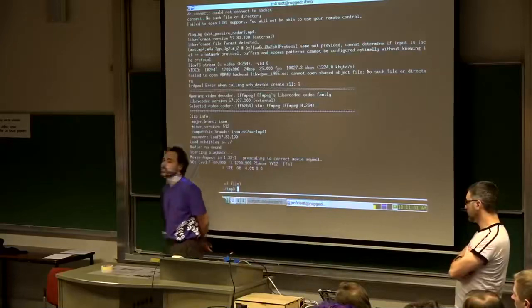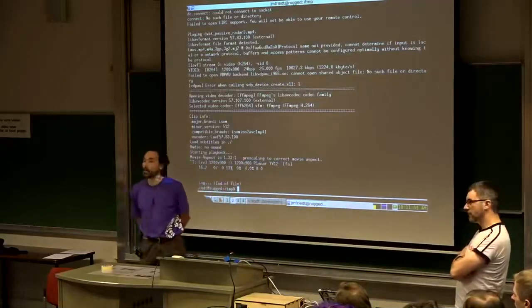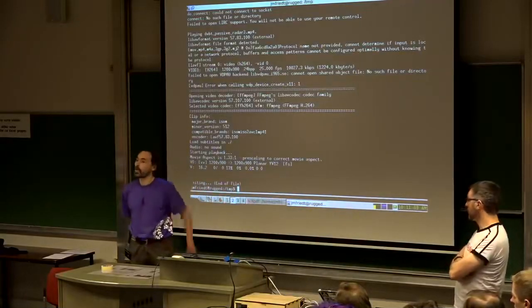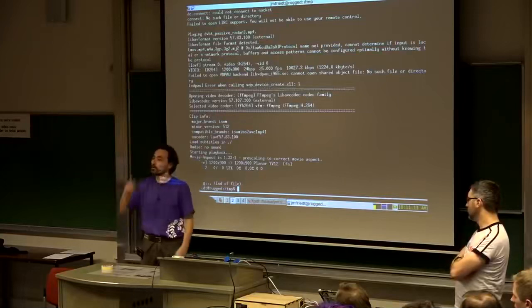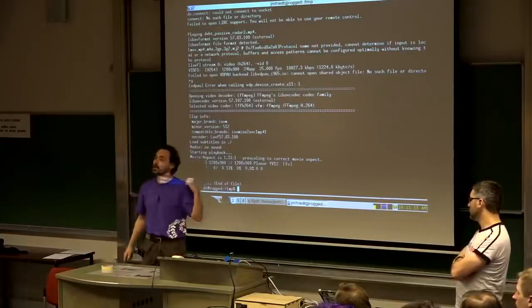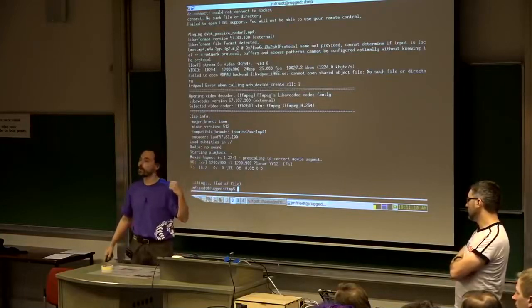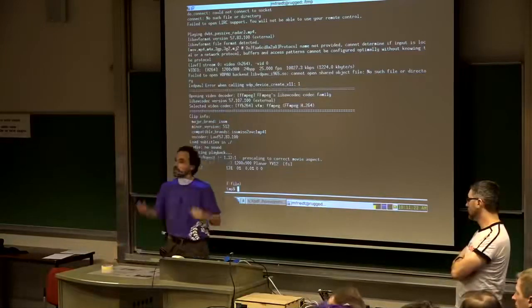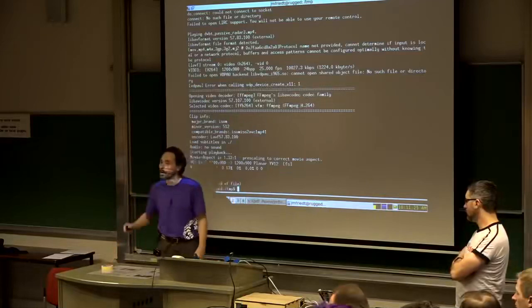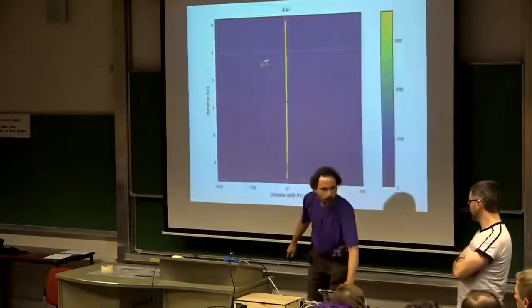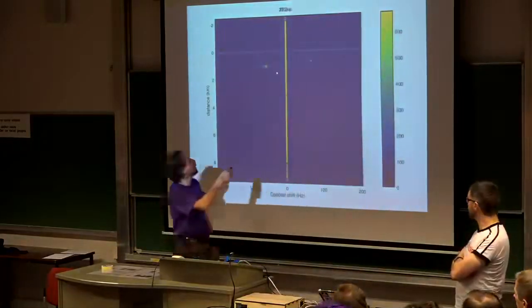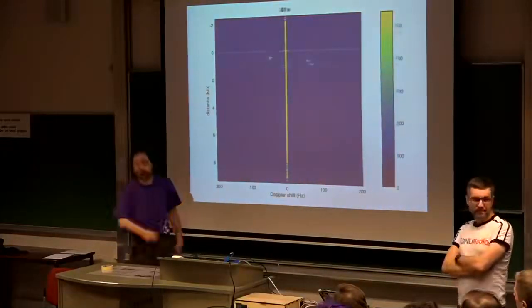Windowing will definitely strongly improve your side lobes. I am not using any windowing in these applications. I'm using long enough correlations so that my signal-to-noise ratio is sufficient to have a single pixel in my correlation. Obviously, windowing in the autocorrelation function makes a huge improvement on your side lobes. All the data that I'm showing here are not using windowing. Did you give up your resolution? I waste a little bit of the resolution, but yeah.